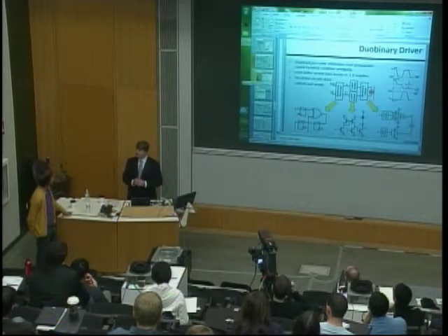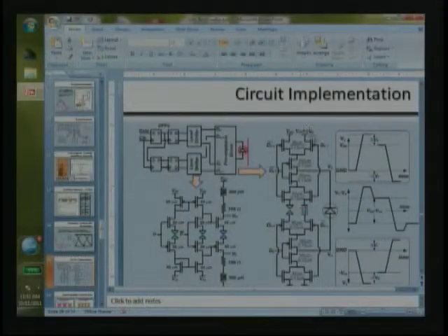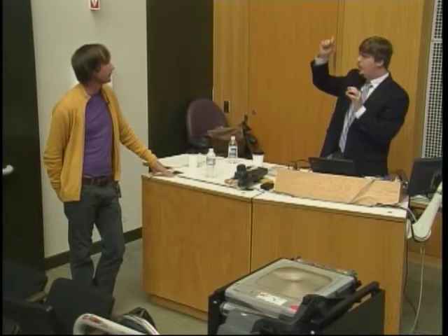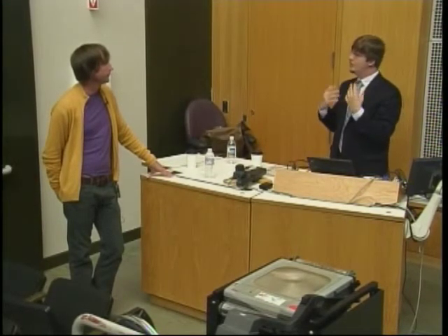Just power. It's a small savings because if you're dealing with duobinary, with equiprobable ones and zeros, then a lot of the time you are going to jack the voltage up and down. But in the end, you consume a lot more power going to the higher supply rail. The other thing is if you always keep the supply high, you don't get the pre-emphasis bandwidth compensation. It's really the waveform that jumps up to the higher value that provides you with the bandwidth compensation.